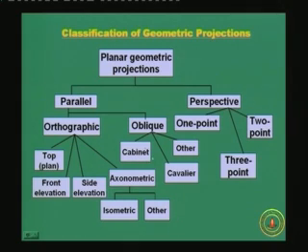The two different types only we will discuss: what is oblique type and how it is different from axonometric or isometric type, and that is again how it is different from the front, top or side elevation. So, first we will move towards orthographic projection, talk about top, front and side elevation views, then move to axonometric, isometric, one example each, and at the end we move towards oblique projection.